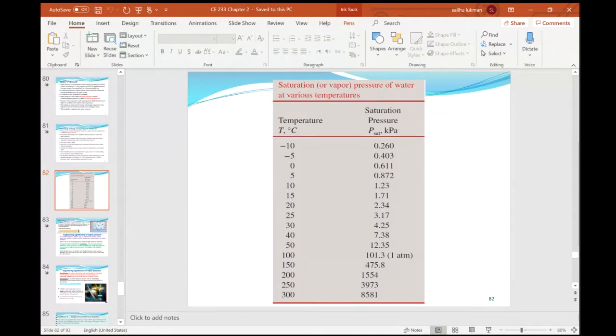Once the local pressure is reduced and the water temperature is at 50 degrees, then it will begin to boil, because at that point, the vapor pressure will be equal to the local atmospheric pressure. Boiling is simply the formation of bubbles emanating from the bottom, coming up to the surface and bursting. And then you have the phase change from liquid to gas.